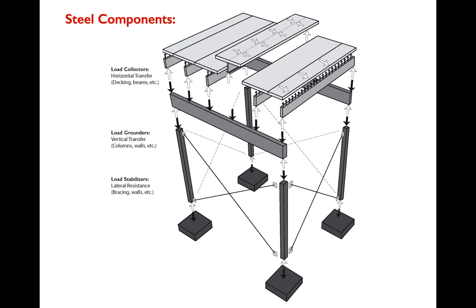But the rolling process, because it's a linear process, is very good for linear elements like columns. And there's a particular set of shapes that we'll often use called compact sections that come close to the radius of gyration value for hollow tubes, but without the expense of rolling those. We can, of course, roll steel into hollow tubes as well. A little bit more expensive, but if we're exposing those columns, then it may be something that's worth the budget to get an architectural shape.